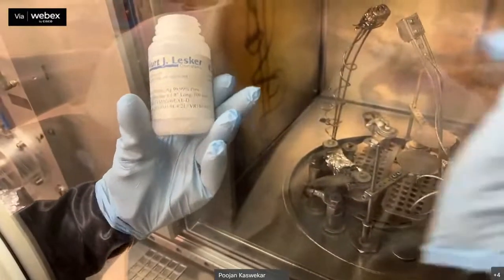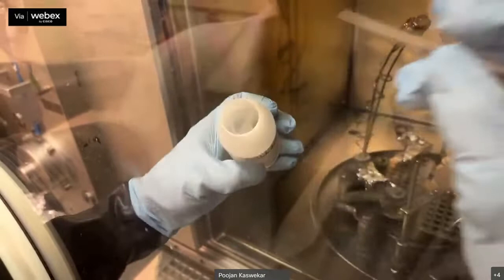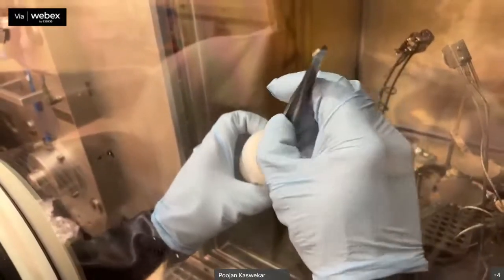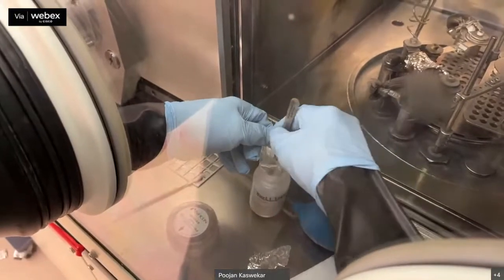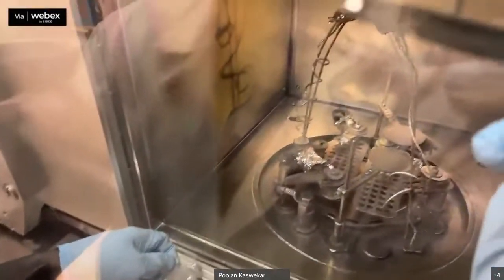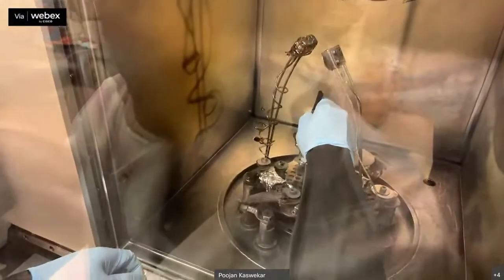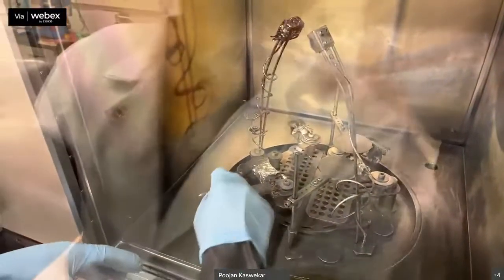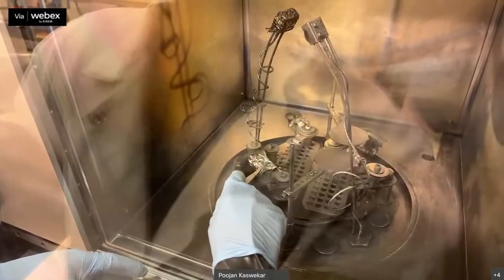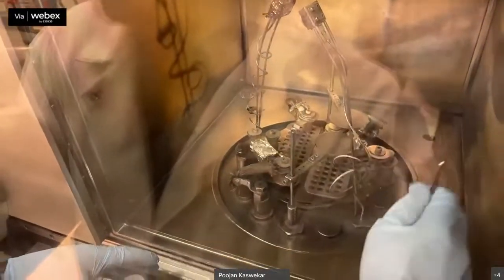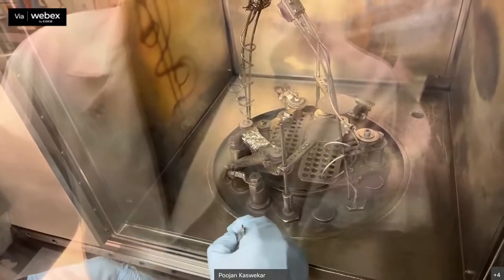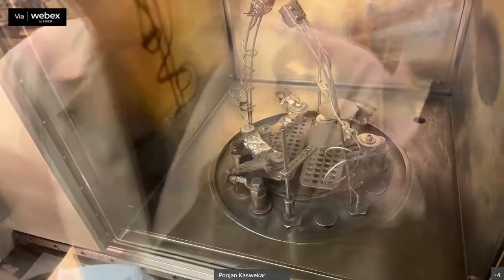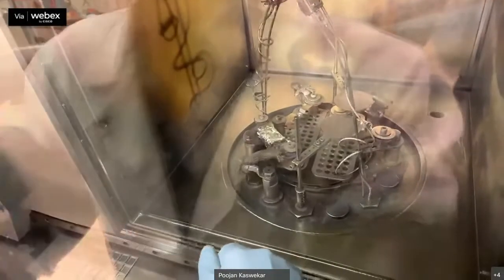These are the Ag pellets with 99.99% purity and 1.8 inch diameter. One pellet should be enough to deposit 100 nanometers of film, and we are going to deposit about 85 to 90 nanometers here. This is the silver pellet we're going to use. I covered the remaining 2 boards: this is the board for C60 and this is the board for depositing BCP. Depending on the material, you choose your power. Normally silver deposits at a power of 20 to 23%. After experiments, you will know which power is good enough. We will deposit 85 nanometers of silver in 25 minutes.